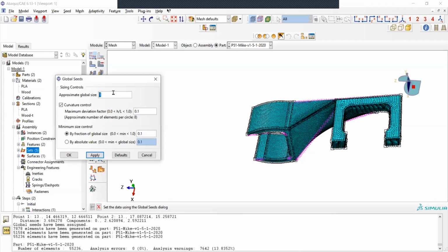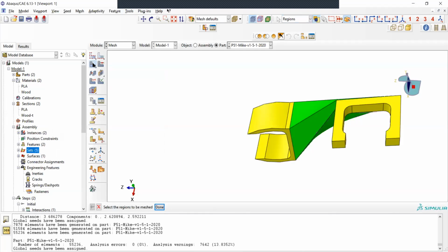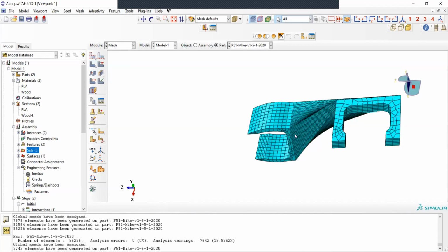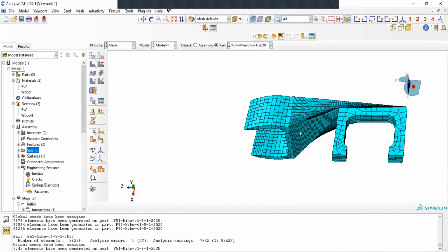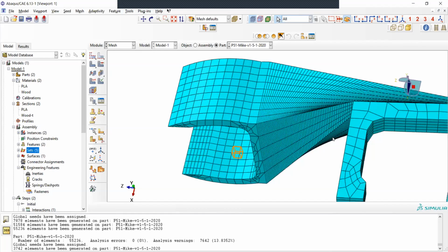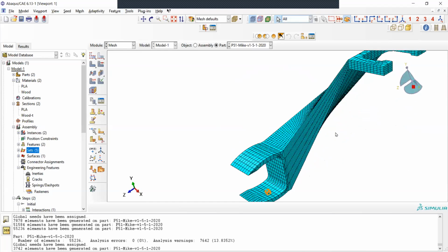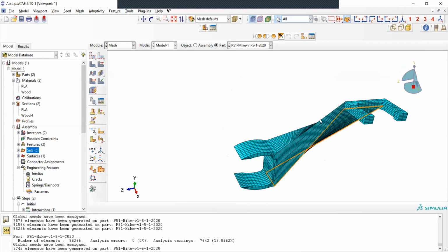So just for the sake of this simulation, I will keep it as a large mesh, and I will mesh it with the element size of 3 rather than 1. So this is much denser, much larger mesh. And you see again here you have a curve. We have to divide it by 5. So there's a lot to still improve. But for now, I will stop here, and meshing on its own is 1 hour or 2 hours of time just for the meshing. Let's move forward to the final step, which is job.